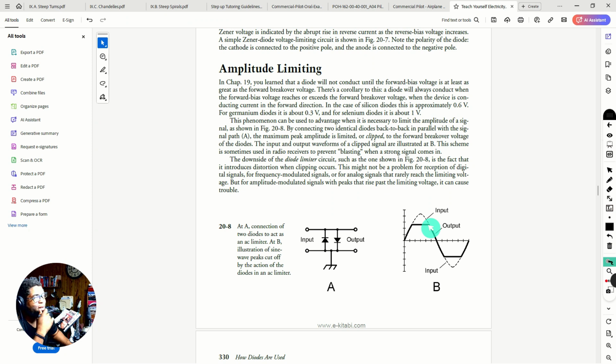In an audio setting, like a guitar distortion pedal, the idea is really just to build a really bad amplifier, and part of that is to take a clean sine wave and turn it into a square wave, because that's going to be harsh. The sine wave has smooth peaks and valleys, but then you give it these corners and you make it more harsh.